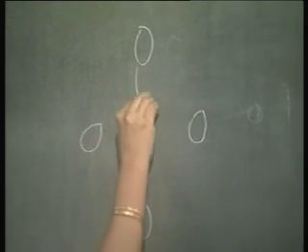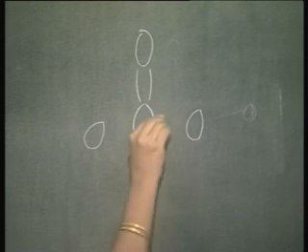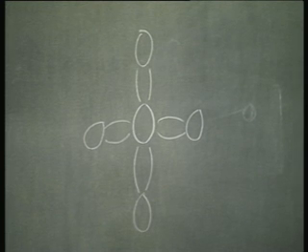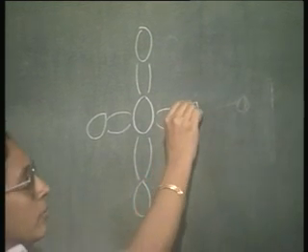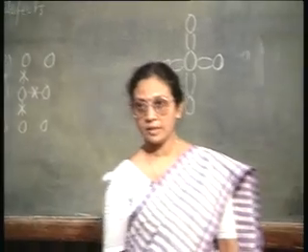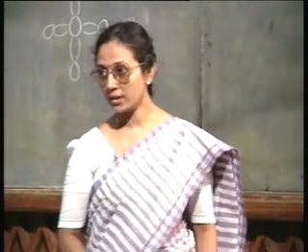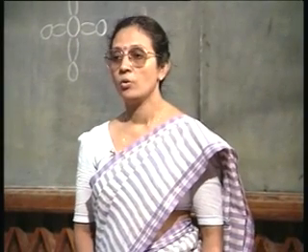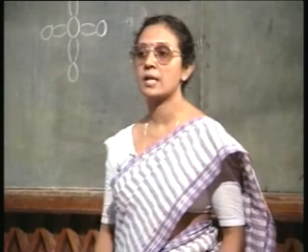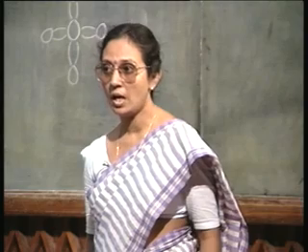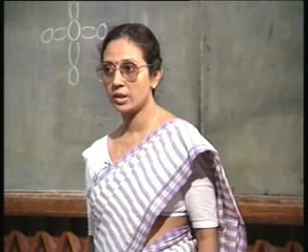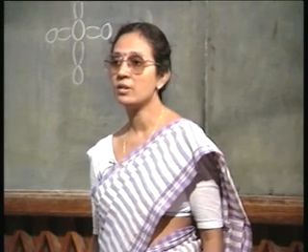You all remember, I suppose, that we say these are the bonds which are formed. Right? And if I have a trivalent or a pentavalent atom, then I will have one excess electron or one hole. So, if I have an excess electron, as is the case of a pentavalent atom, I will have a donor. If I have a trivalent atom, then I have a loss of electron or a hole. So, then I have an acceptor.